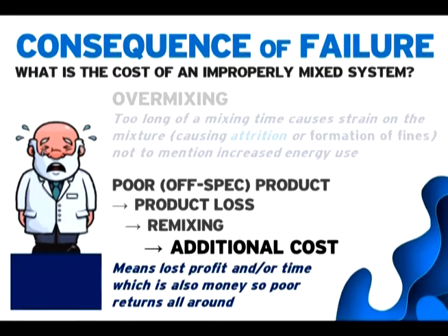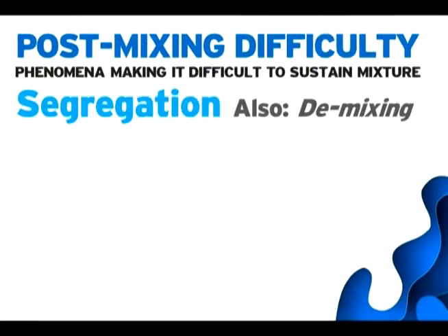Effects of poor mixing may be apparent if mixing occurs as the final operation, but mixing is usually an intermediate operation. As such, its effects on the final product may not be observed until the end. Now, we mentioned that intermediate operations can affect the success of mixing. For the most part, downstream processing, compared to feed preparation, may destroy the product quality more due to a phenomenon called segregation. We can treat segregation as the opposite of mixing, or just see it as a divergence from the desired homogeneity of the product.